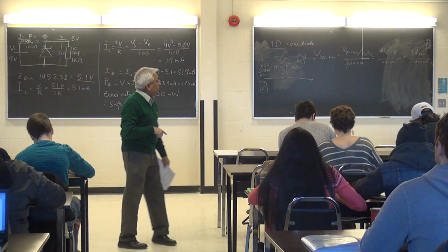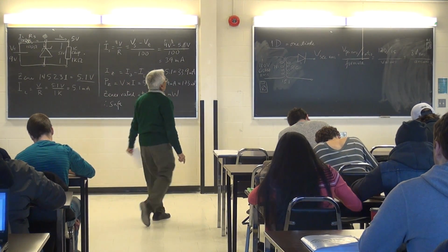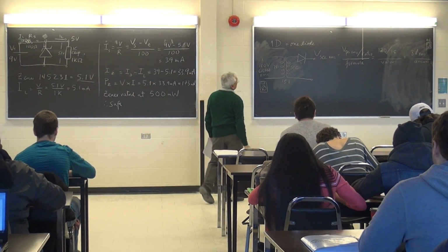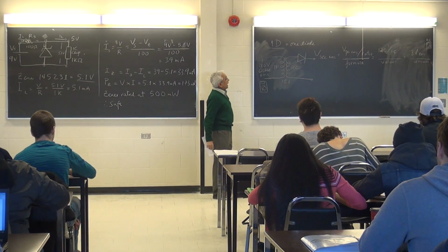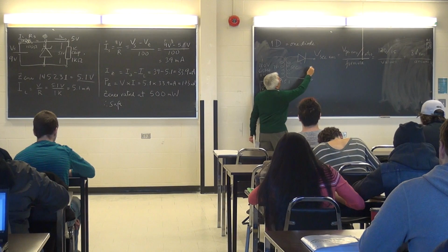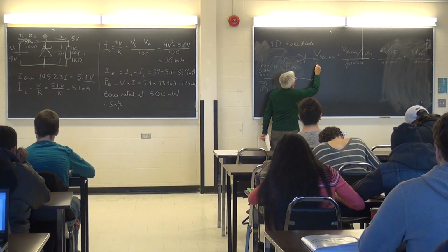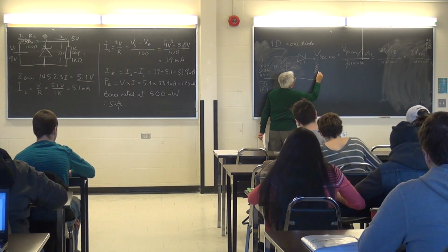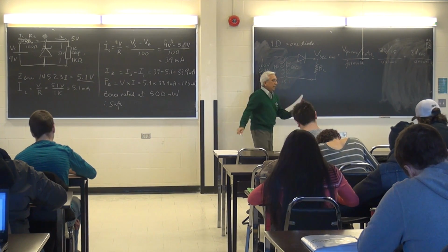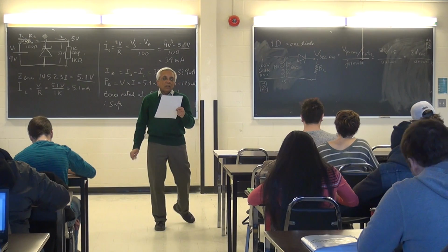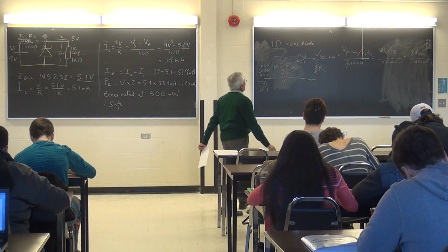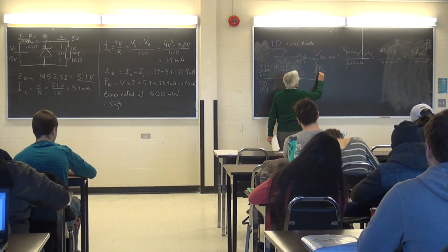The diode will change the sine wave into a pulsating DC voltage. So let's explain how that works. Let me first show the load connected here. So this is the load. The question says that a 1K ohm resistor load is connected to the circuit. So this is 1 kilo.